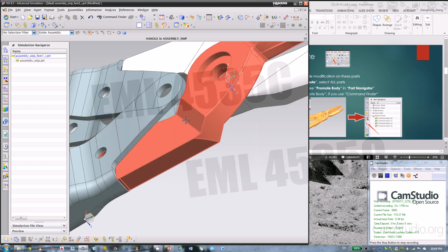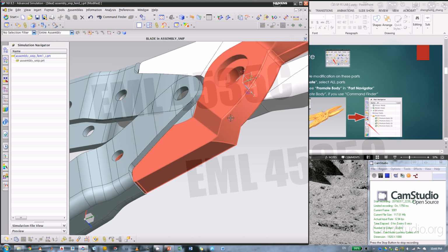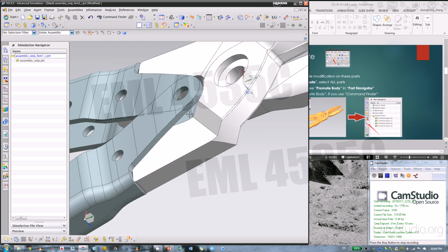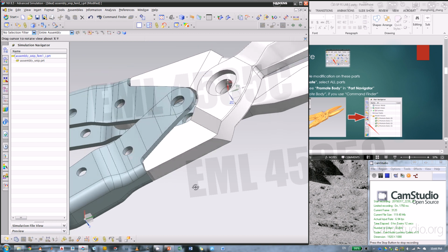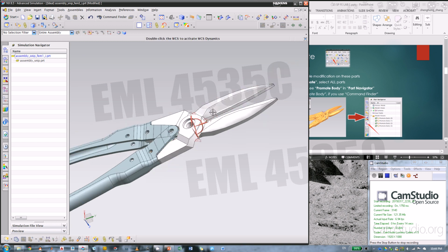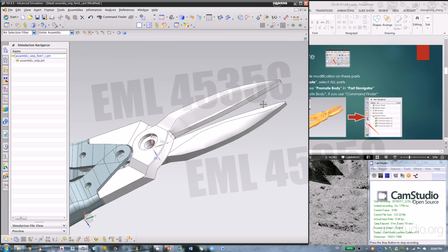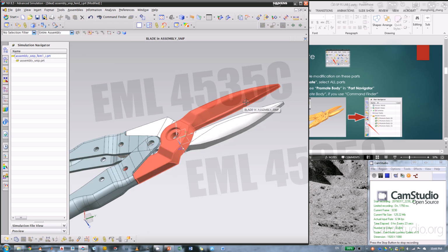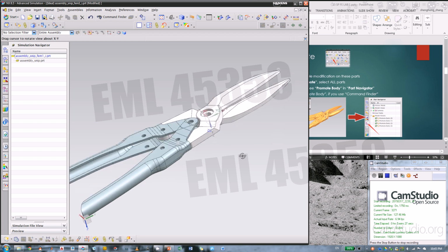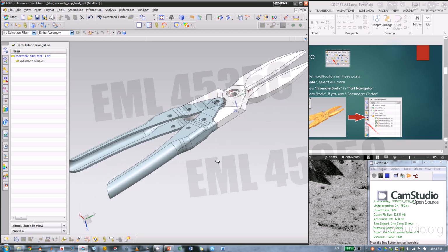So we need to cut this blade into two parts. Then for the bottom part, we're going to use the shell elements. Then for the top, it's sort of not regular. It's not shell, not a beam, so we will use 3D tetra. So that's the plan, and that's why we need to modify the CAD.